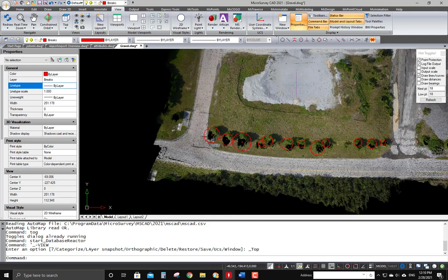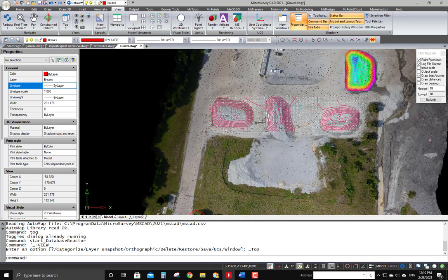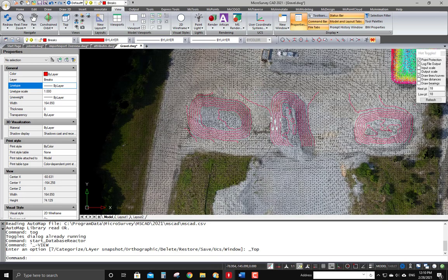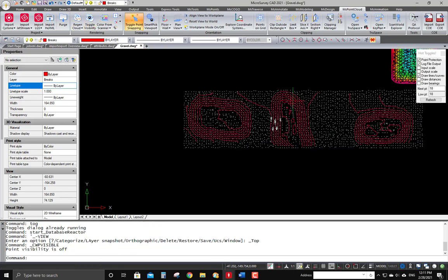Here we've just inserted some tree symbols and sized them to match what you can see in the drawing. Very often what you'll want to be able to do is generate a digital terrain model, and we've used another tool that allows you to quickly survey the point data and generate a kind of grid that represents the bare ground surface. And here I'll just hide the point cloud temporarily so you can see what we've done, and I've used those points to create contours and plot the contours.